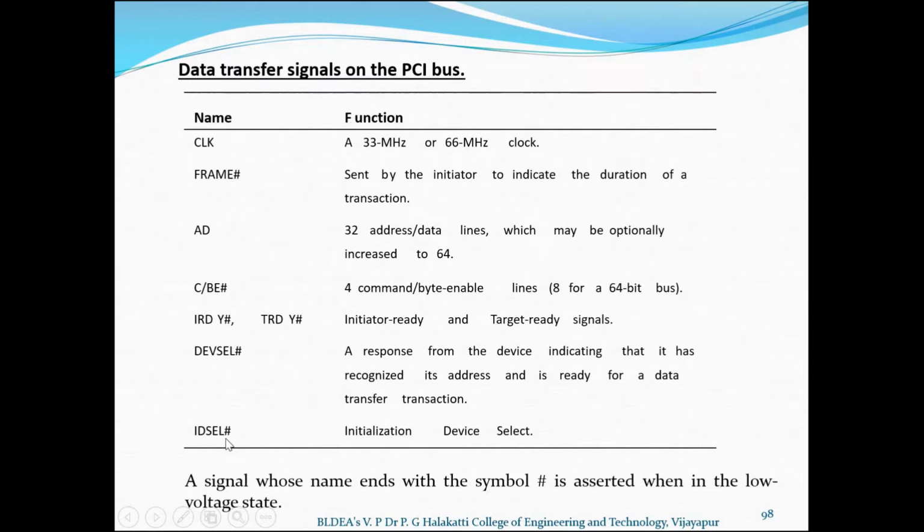IDSEL# indicates initialization device select. Now a signal whose name ends with the symbol hash is asserted when in the low voltage state.